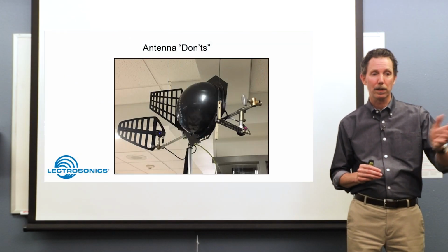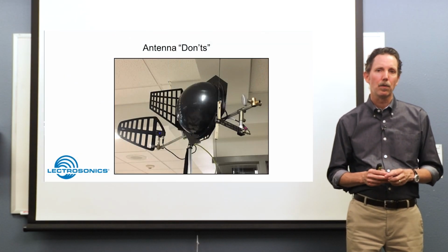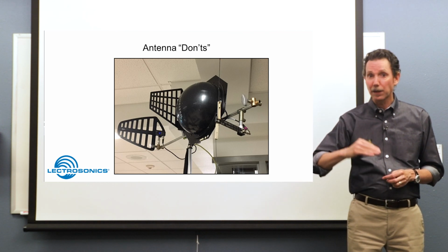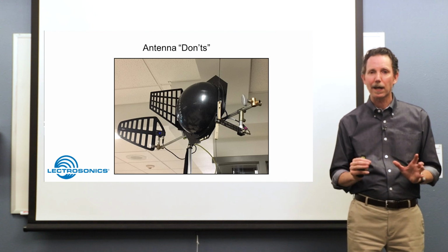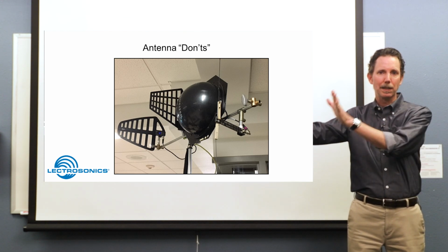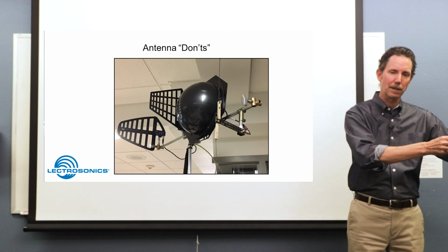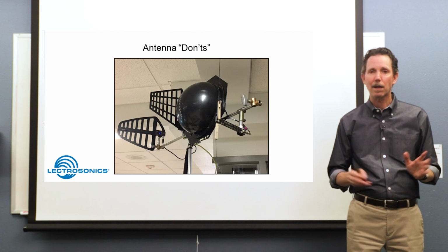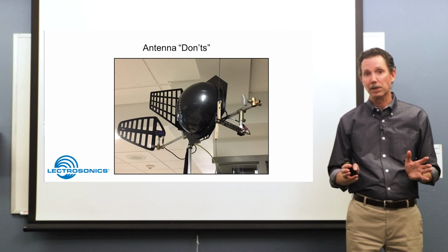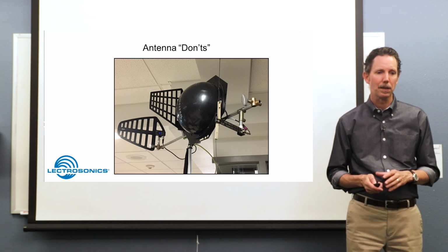So in this particular case, they told me that they were running into some problems with dropouts with their wireless mics, and it seemed to start happening after they added the active antenna, the one on the far left in the picture there. So we dialed the amplification of that antenna down. We'll get into details about that. And I suggested that if at all possible, they should separate their transmit antennas onto a different stand and have your receiver antennas physically separated by as much as possible. So I don't know if they've done that, but I haven't heard any complaints. So I have a feeling that they may have followed some of that advice.